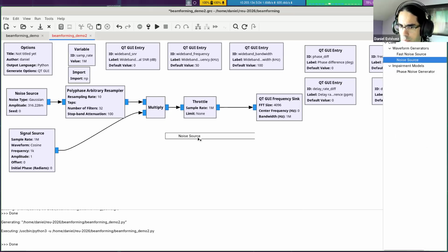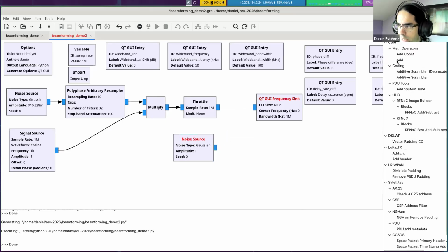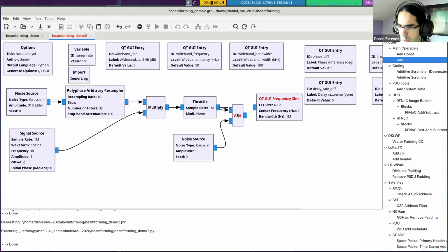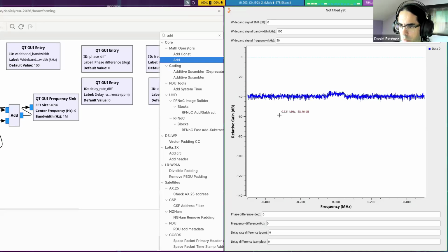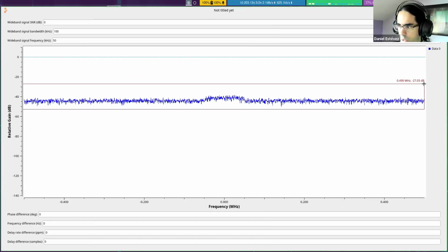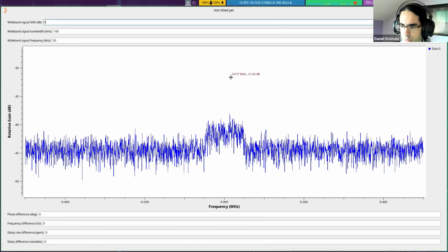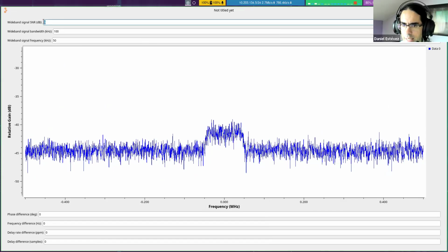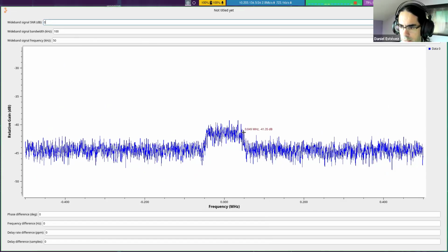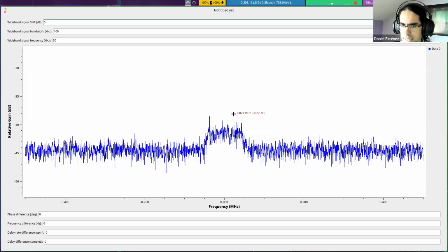But at the moment, for the sake of the explanation, what I'm going to do is add a new noise source, which has an amplitude of 1. So that means the noise power will be 1, to get essentially the thing I wanted to show here, which is this. And now what's happening is the signal to noise ratio is defined as 0 decibels. Let me put more averaging even. So that means the power of this noise source, which is going to represent our signal of interest, our astronomical source, is the same power.